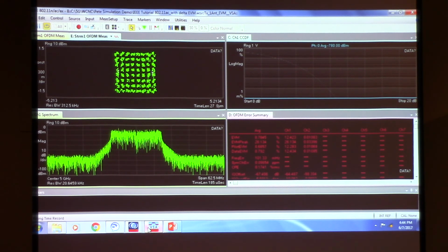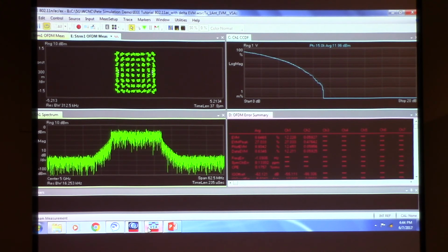Yeah, so that was a bit extreme, but clearly you see that any sort of phase imbalance can impact the performance as well. So we have to be pretty careful about dialing these in, maybe doing some calibration if we were generating a signal with a signal source. And likewise, if you have an analog IQ modulator in the transmitter part of your system, you would be concerned about this as well.